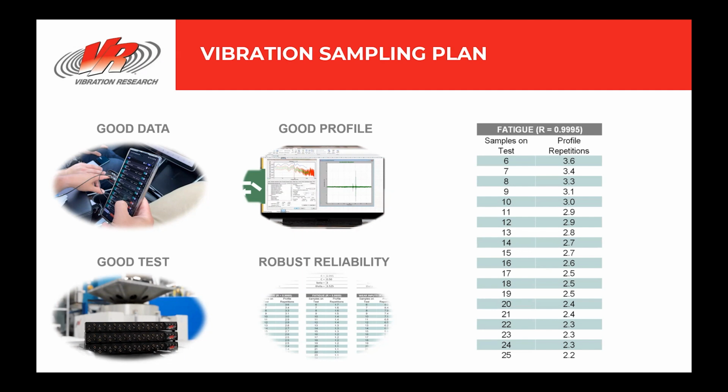If this is not practical, due to not having prototypes available or lacking suitable data acquisition hardware and knowledge to make measurements, or not having accessibility to a representative environment to record good data, then surrogate data from a similar application or from past experience or from an industry standard or online source is the next best thing and can still be used. Vibration Research makes a great portable economical data acquisition system, the Observer 1000, that can be used to gather good data.